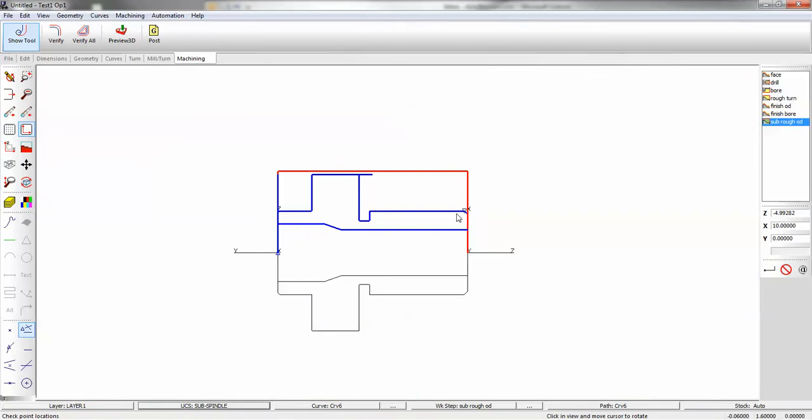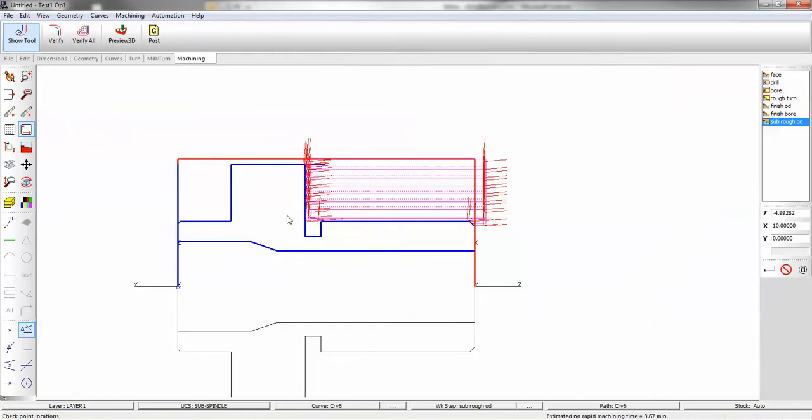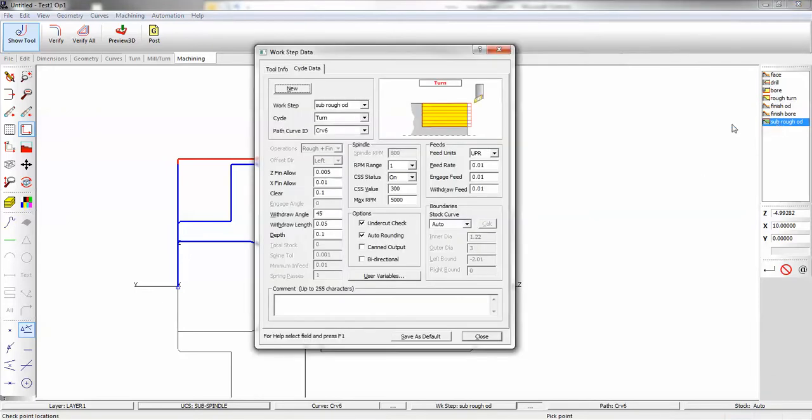And maybe what I'll do, now let's look at the toolpath in the groove. It optimized for the contour, the shape of the insert. So it didn't violate that. If we go into the operation, you can see we have undercut checked. Let's click on that. You can see the graphics. There's the tip of the tool. Tip of the tool plunges into the groove.